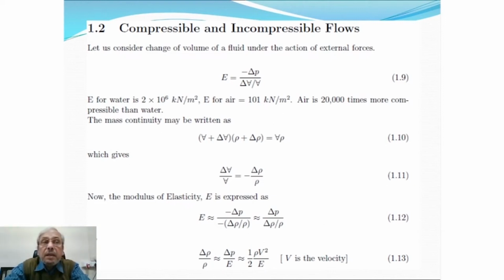We can write, pressure is being applied, obviously fluid is flowing, and since pressure is being applied, its volume may change. So the modulus of elasticity is minus ΔP divided by ΔV by the original volume.